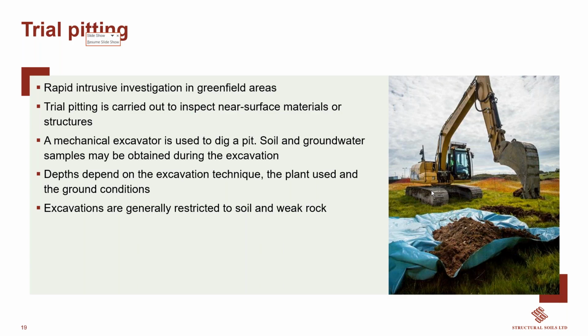The good thing about trowel pits is we can get a huge amount of sample in a relatively short amount of time. This particular site was up at Wilver, and the material was very granular, and we needed to take a huge amount of sample to make sure that we had enough for the compaction and the testing required. So by lunchtime, I'd probably done 2 or 3 trowel pits, and I'd almost filled the back of a Hilux on this particular job.